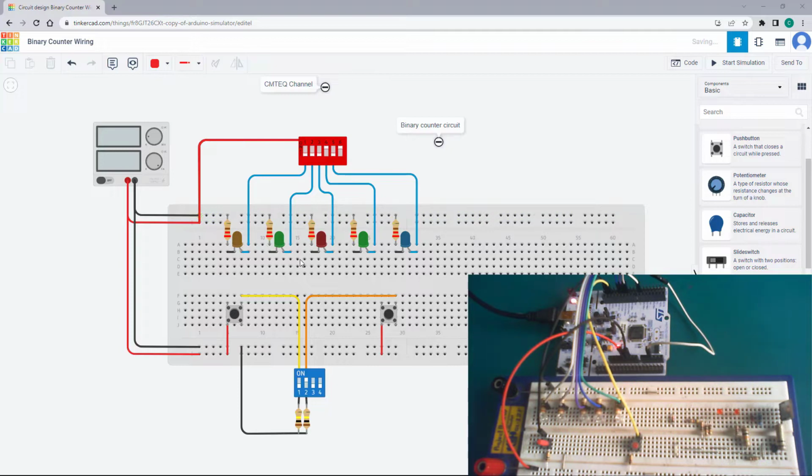Now the 5 LEDs are connected in a way that I've got the cathode of each LED connected to a resistor and going to ground. All the resistors are 220 ohm and they are all connected to ground through the cathode of the LED. And the anodes of the LEDs are all connected into this block of connection here. Now let's say this is my GPIOA register on my STM32. So this will be either pin 4, 5, 6 or whatever the case may be, where all these LEDs are connected. And right down here I've also got my 2 push buttons.